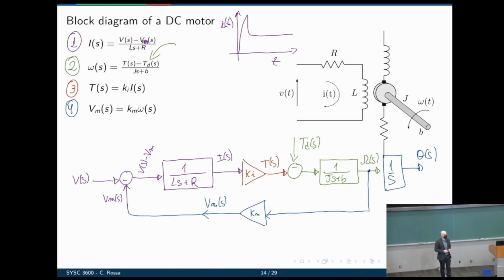So when you buy a motor, you typically have the nominal current, which is the current after everything's settled, and you have the stall current or stall torque, that is the maximum current. For a small DC motor, if you get one from Maxon, they are like 40 millimeters in diameter, the stall current is something crazy like 80 amps, and the nominal current is 2-3 amps. And that's because of this feedback loop. The system cannot, of course, sustain that for long. It will simply destroy the armature. But that phenomenon happens, and typically lasts a few milliseconds if the motor is constructed well, until it starts to speed up.